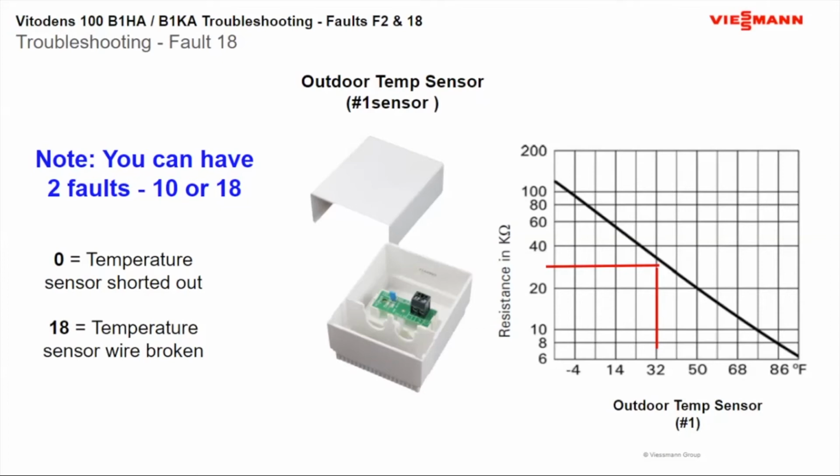Guys drill the hole for their venting, and then, hey, if we drill the hole, I can get my thermostat wire there and hang it right above the exhaust pipe, and wonder why the boiler's not working. It's fooling the sensor into reading that it's warm. So that's why I always like to bring that up. So make sure that it's jiving and make sure it's in the right location.